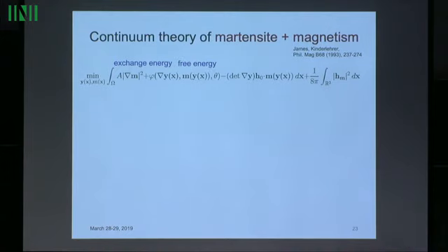The free energy should depend on the deformation gradient. Again, we've condensed out all these shift vectors, and magnetization. But the magnetization lives on the deformed configuration. So the way I like to write it is with composing that with the deformation and temperature.